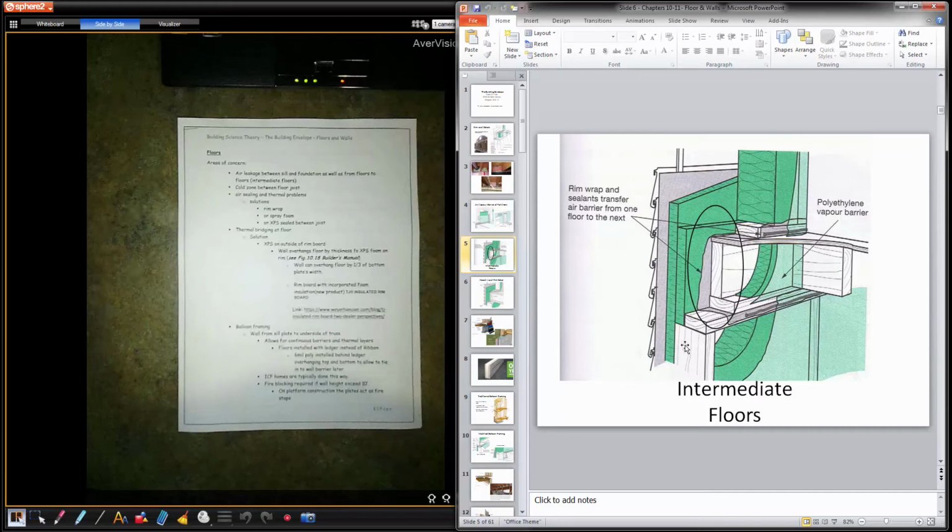So maybe a 2x6 stud. They went with a 2x4 plate, which then allows for 2 inches of foam. So basically using the minimal size of plate possible to allow for styrofoam in front of it. And then you can see the same things happening at the top. It actually shifted the wall out to come in line, which was not completely necessary, but just stays on foam.